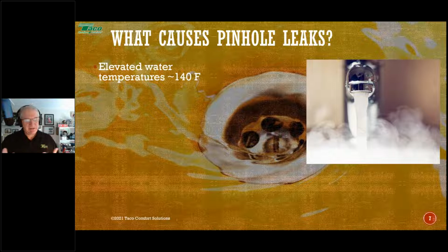Now, it's not something we can really mess with because sometimes we have to make water up to 140 degrees to take care of Legionella and things like that. So it's not something that we can really impact. But there are three others. Let's see what we have here.